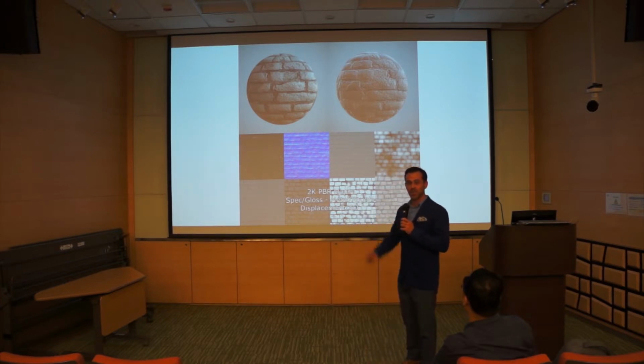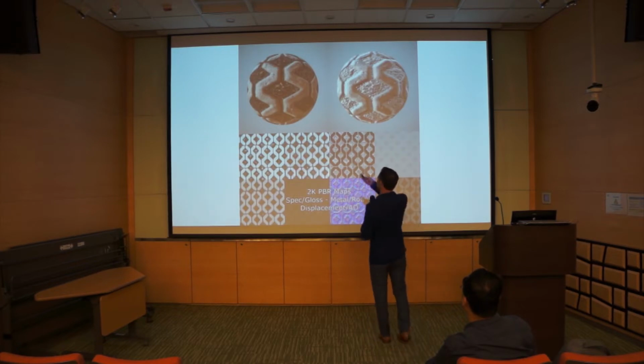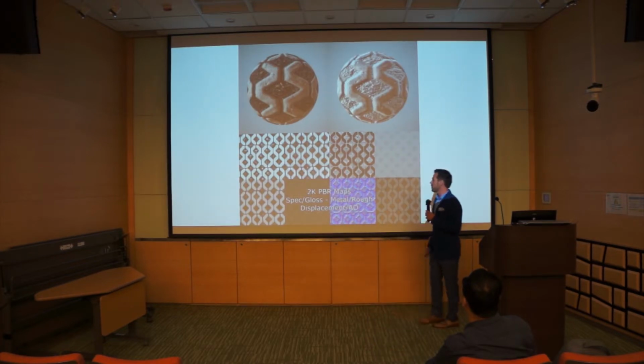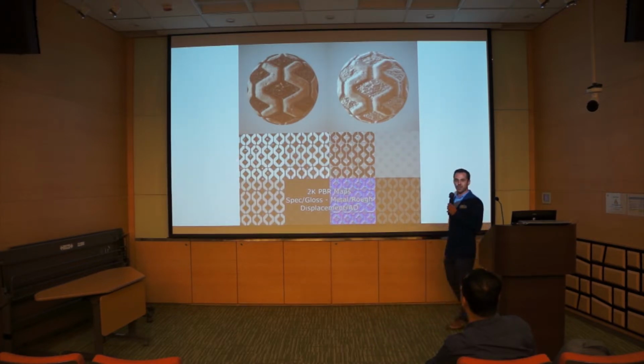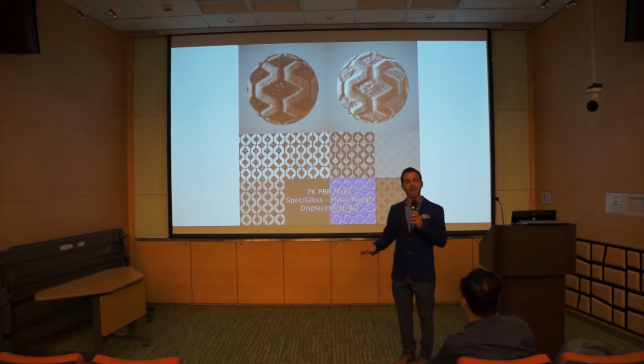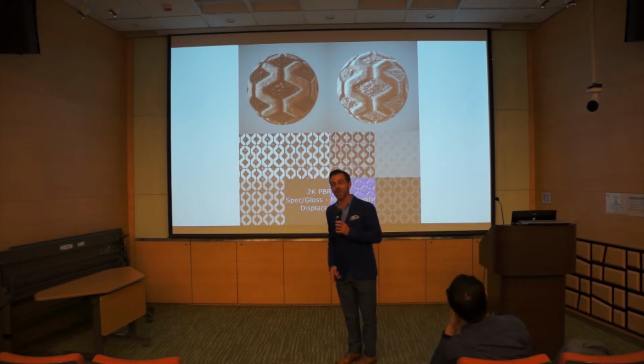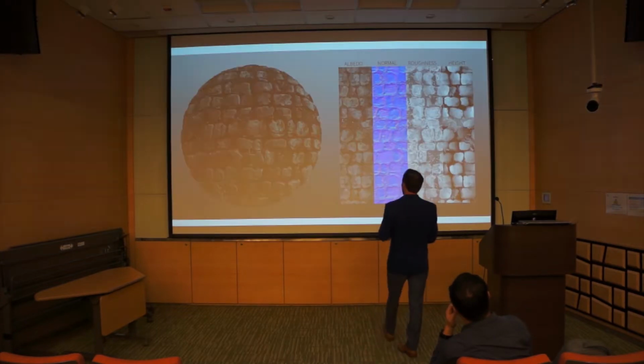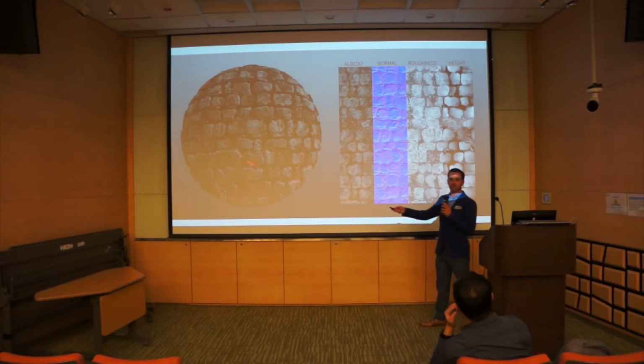Lumion and SketchUp use a 1 or a 2-map system. So what does this mean? What do these maps do to the material? Well, what happens is we start off with a texture map, or the albedo map, and then you replace the bump map with a roughness map. And then you add a metallic map. And then you add a height map. And then you add an ambient occlusion map. And what you result is these very rich materials.